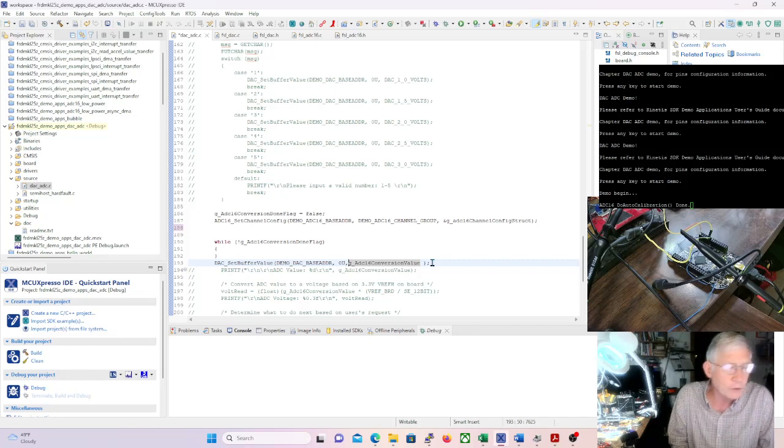So what you have to do in the signal generator is set the amplitude to 3.2 volts, a little bit less than 3.3, and then put in a 1.6 volt positive offset so that the whole thing varies from 0 to 3.2 or 3.3 volts. And so then that'll work with the PIC, with the KL25Z, and also with the scope and whatnot.